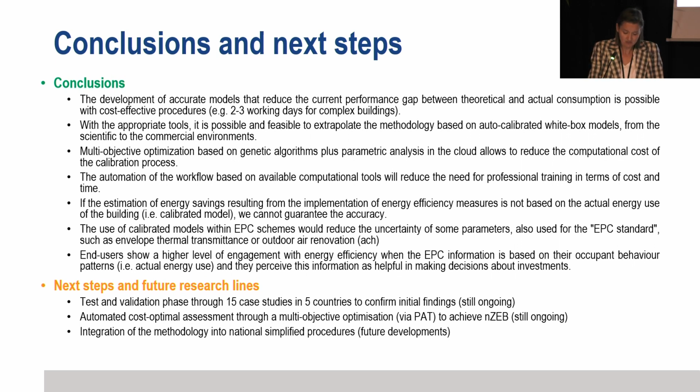The use of calibrated models within EPC schemes would reduce the uncertainty of some parameters, such as the global thermal envelope transmittance or the outdoor air renovation inside the building. So when we fix the values for these calibration variables, we use these values also in our standard model.